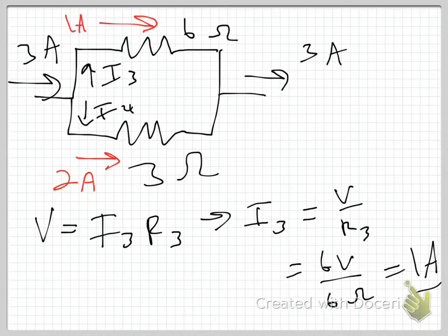And that's exactly what I expected. Remember the discussion: 3 ohms is less than 6 ohms. The resistance of the bottom leg is less than the resistance of the top leg. So I should expect to find more current flowing in the bottom leg than in the top. It's easier for it to do so, and I do. And please notice that the currents I found are inversely proportional.